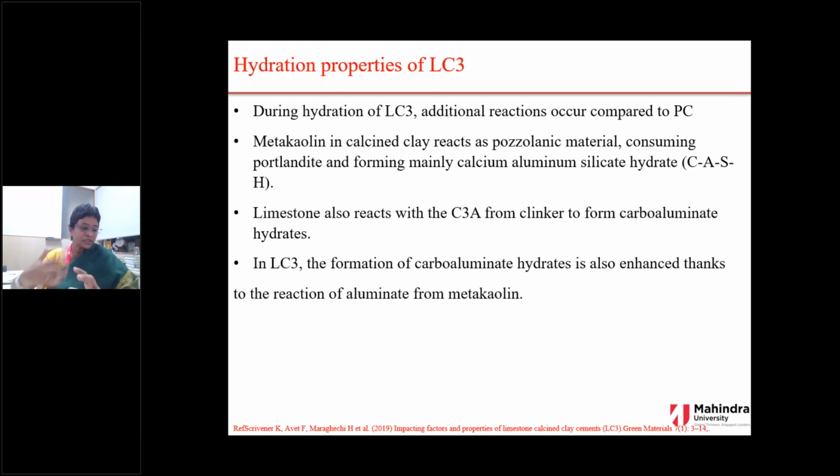What do these phases do? The change in these phases gives a better pore space filling effect. Since it has a better pore filling effect, obviously it leads to better mechanical and durability characteristics. Also, the metakaolin in the calcined clay reacts as a pozzolanic material, consuming the portlandite and forming C-S-H. So we have extra C-S-H being formed.